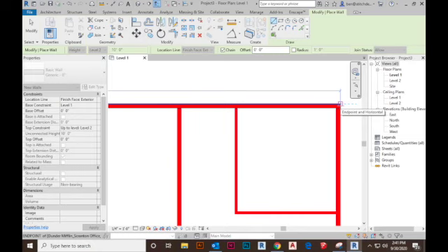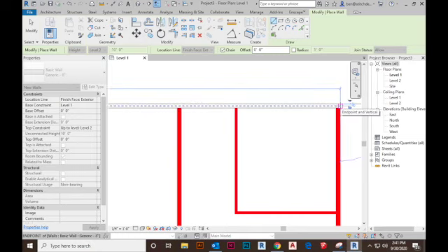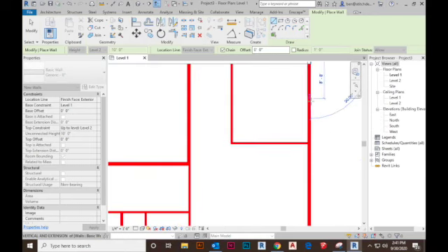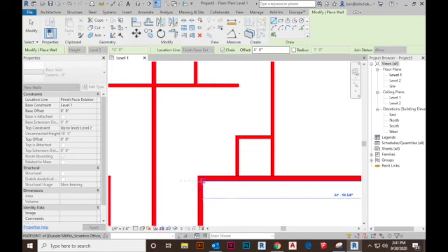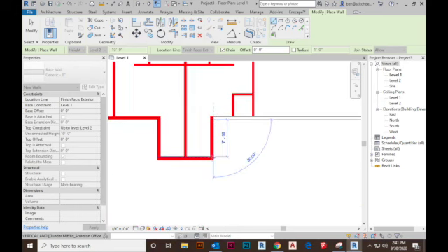I'm going to click to finish that wall, and I see no red on that line where I drew, so I know I've covered the entire length of the wall. And now I'm going to start going in a plan south direction for this east exterior wall and continue drawing the outside perimeter based on my CAD underlay.